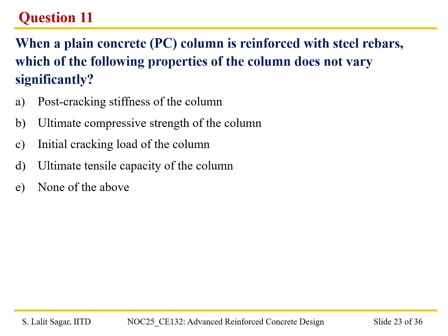So here, in option A, we are basically talking about its compressive behavior, right? The post cracking stiffness, the ultimate compressive strength, again the compressive behavior, and then we have the initial cracking load, which is the tensile behavior, and then we have the ultimate tensile capacity.